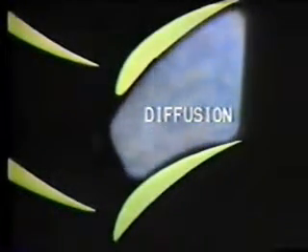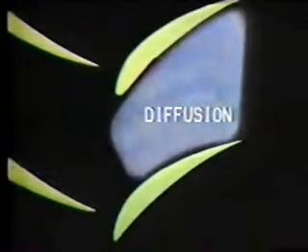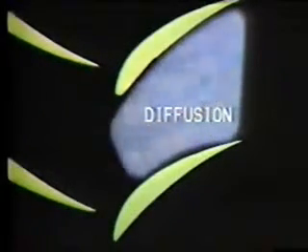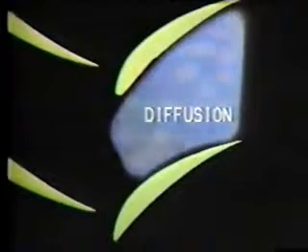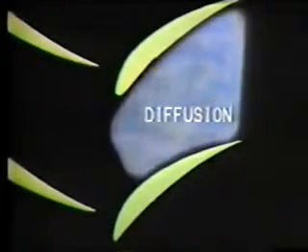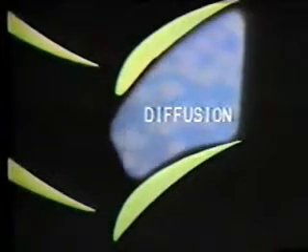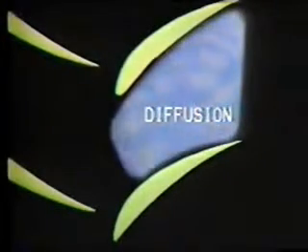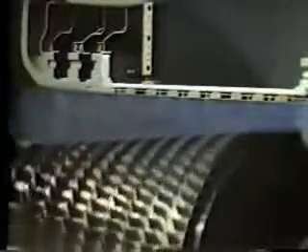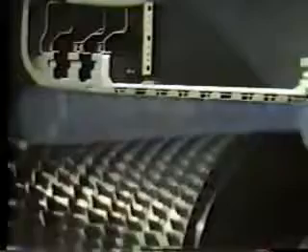It's at this point, in the spaces between stator blades, where air is slowed down and we gain air pressure. This is called diffusion, and it is the key principle which makes the compressor work. The space between rotor blades acts as a diffuser too, slowing the air velocity. Won't the air eventually stop if we keep slowing it down? No, it won't stop because two things are occurring which maintain air velocity.